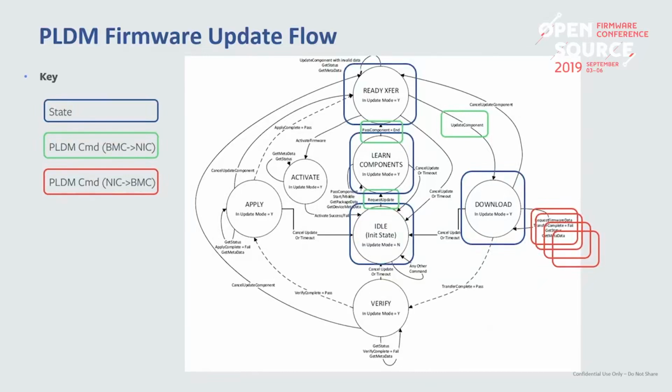So at the end, you'll see a verification fail or signature check fail. If on the BMC side we can keep track of how many chunks have been requested by the device and what the offsets are, it will be much easier to debug down the road. Okay, so assuming there are no issues, the device keeps requesting additional chunks.